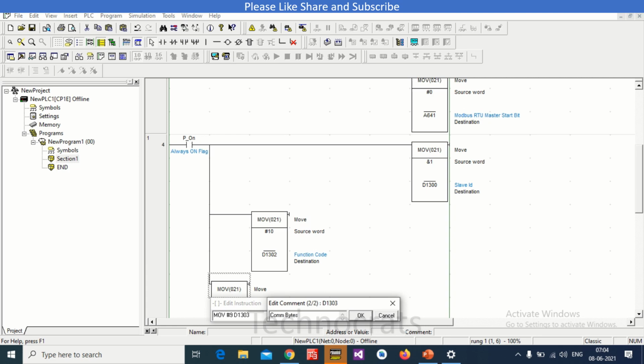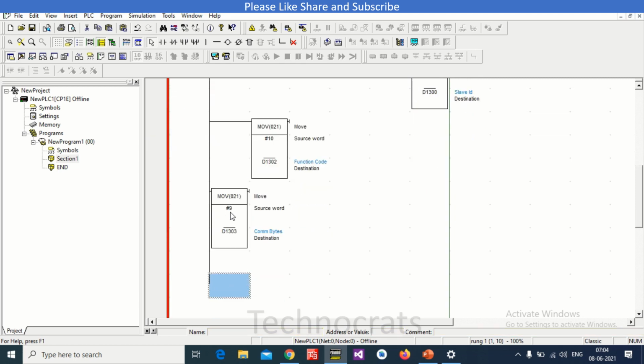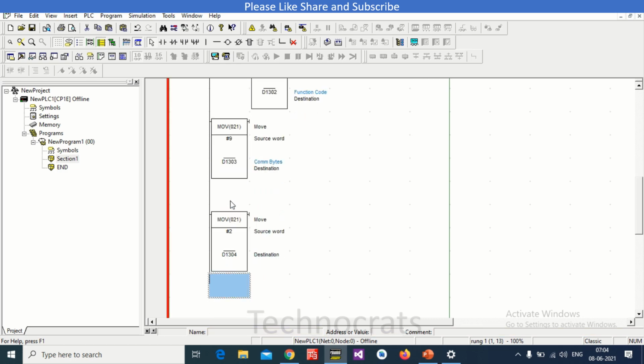Now D1304 is your number of registers to be written, so I will use #2. So here we will give the start command and the frequency to the drive. We are only writing the start command and the frequency.